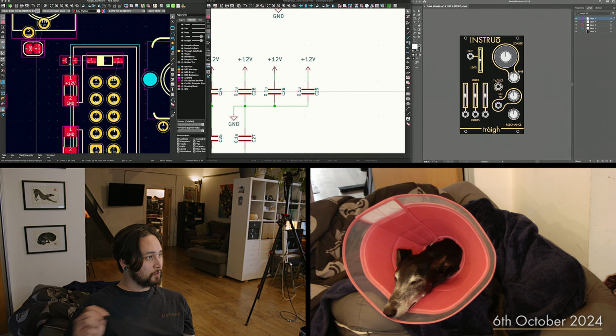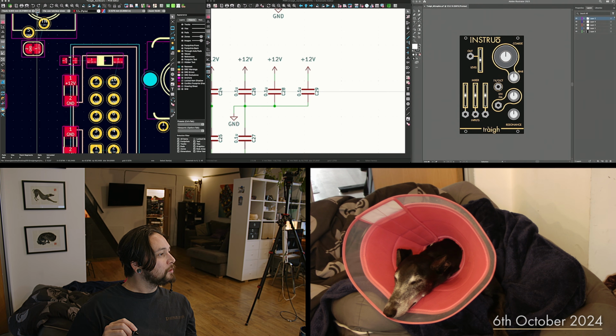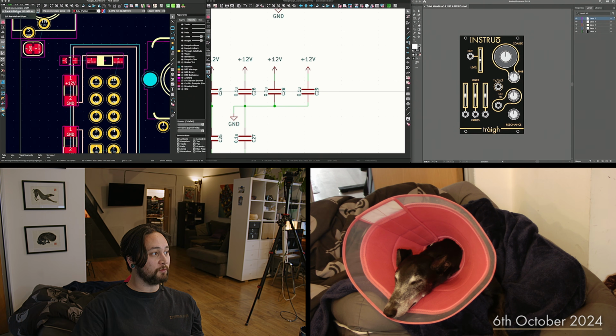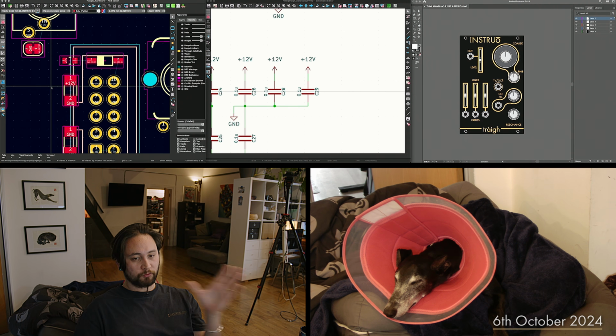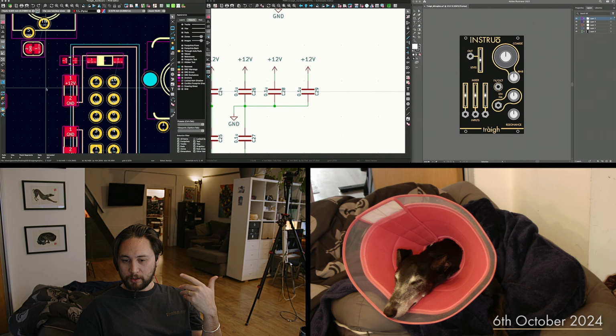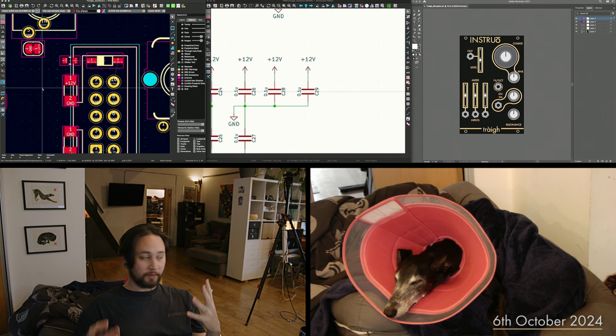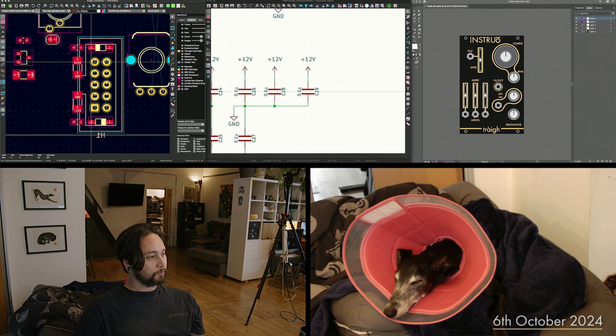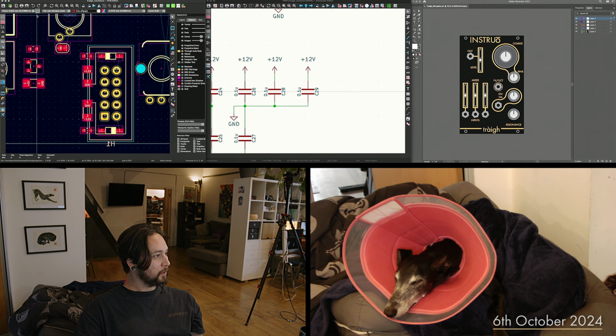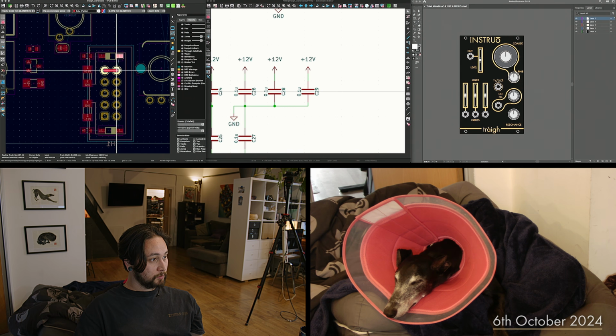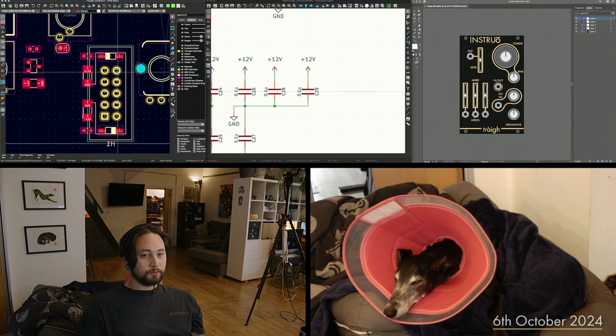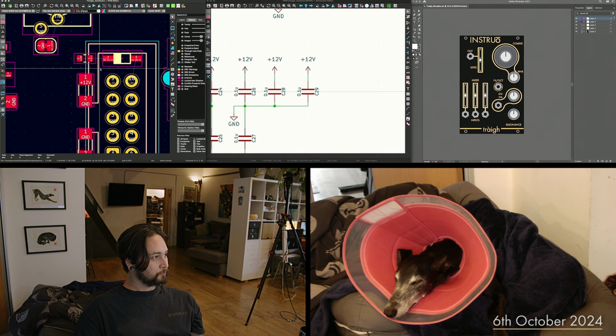This is a useful, I'm not sure what they call it, when routing from an existing track, use its width instead of the current thing. So it'll basically override whatever I've got manually selected, and if I'm pulling from a trace, it will continue drawing at that trace width. So I'll take that off, and I guess here we go.